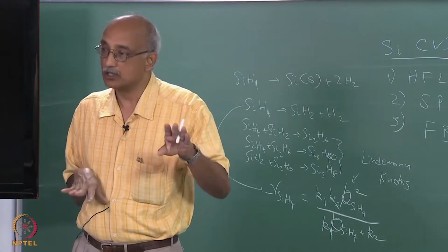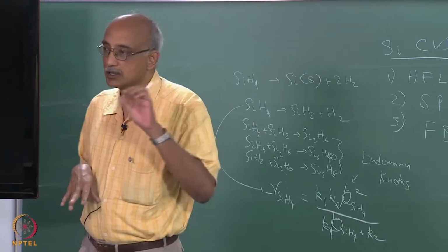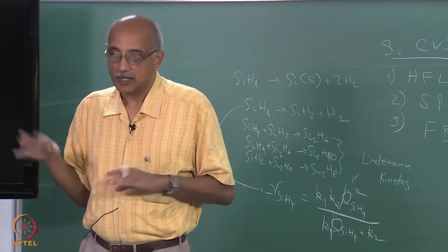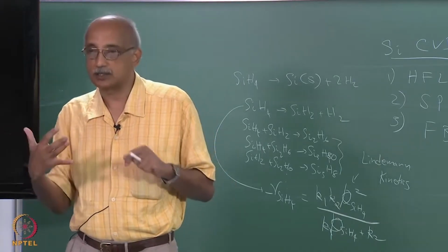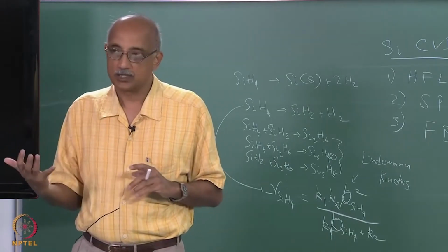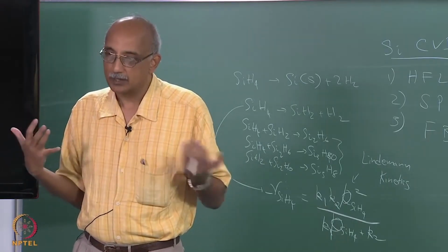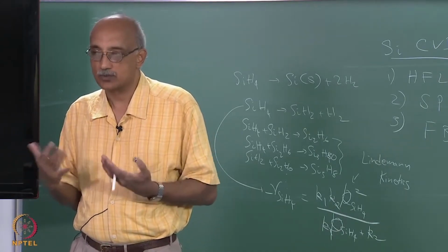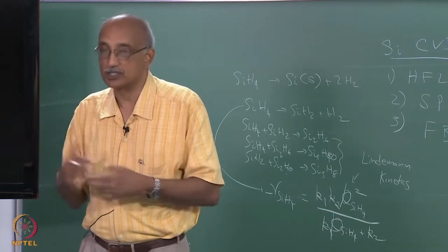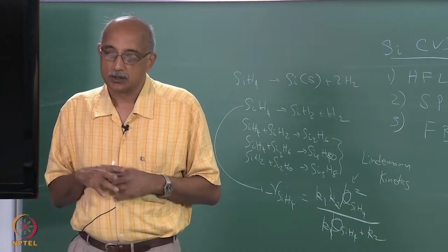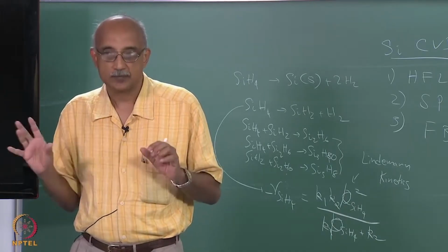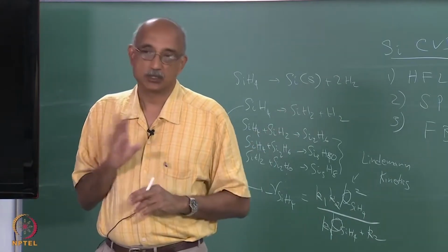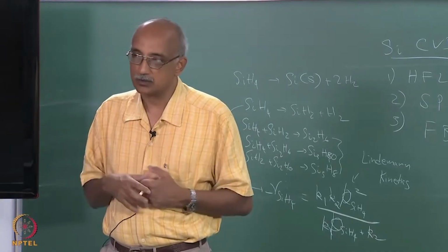You have a model that is very good in terms of describing the flow dynamics and the diffusional behavior, but is kind of weak in terms of describing the kinetic behavior. Whereas, on the other hand, if you are working at the other end, you may have spent a lot of time developing the best possible kinetic model, but then you are essentially going to be taking in the flow dynamics and the diffusion or the transport phenomena as again a user supplied subroutine. It is very difficult for a single research group to have sufficient expertise to deal with all the 6 aspects in sufficient depth, and so you tend to sacrifice one or the other.